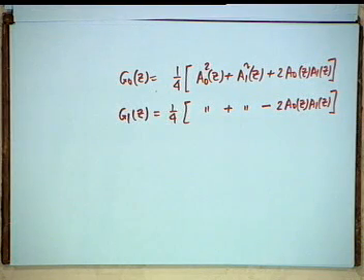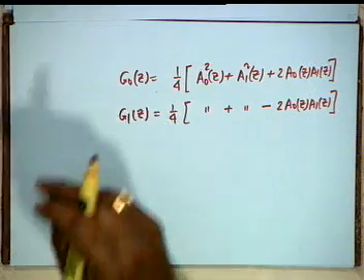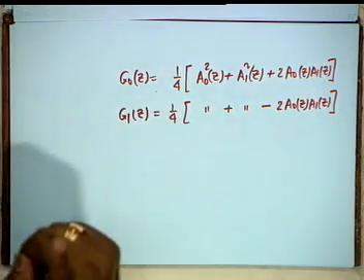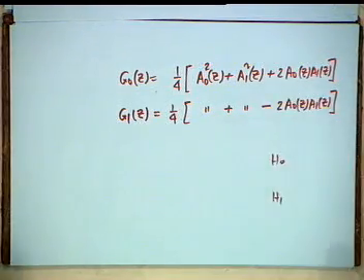Is there any question on this? On the magnitude complementary? We just took a simple example from what we already know. And getting a magnitude complementary filter is also not a problem. What you do is you cascade the two such blocks, the blocks which realize H0 and H1, that is, you start with the same all pass filter. One is 1 and the other is minus alpha plus Z inverse divided by 1 minus alpha Z inverse, and we showed how to realize H0 and H1. Just add one more of this.